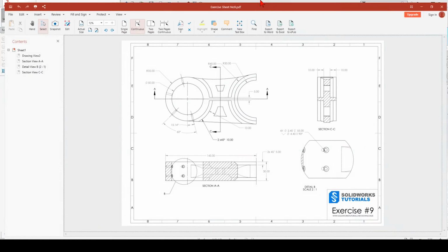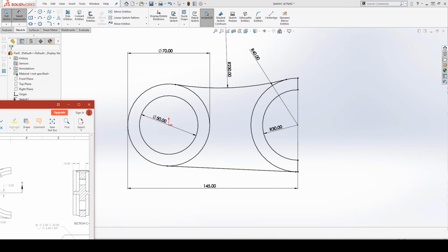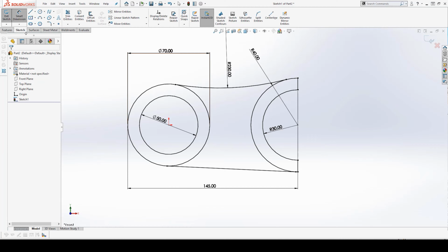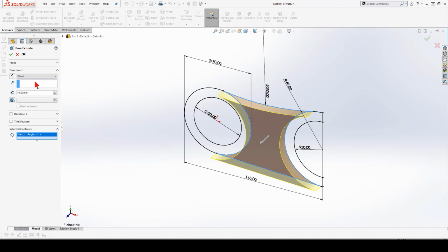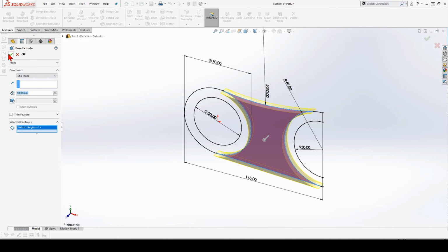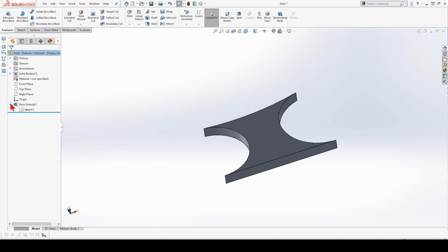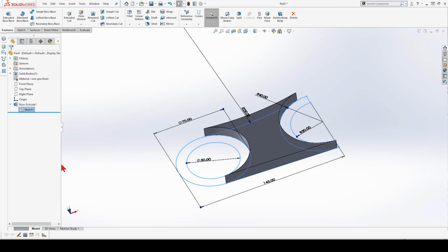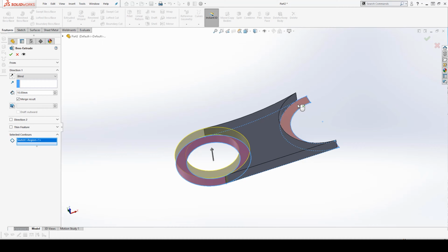At this level, I'm going to move on and do some extrusions, which is 30 on the outer, and we have 2 times 10, which is the cavity which we see here in the dashed lines. So 10, 10, 10. In this case, it means this area in the middle is extruded 10, and these two circles are extruded 30. Let's start with the middle. I'm going to go mid-plane. You don't have to, we can go blind as well. 10. Reuse the sketch by opening the combo, selecting the sketch, leaving it highlighted, then directly clicking on extruded boss, and over here I can select the other areas.